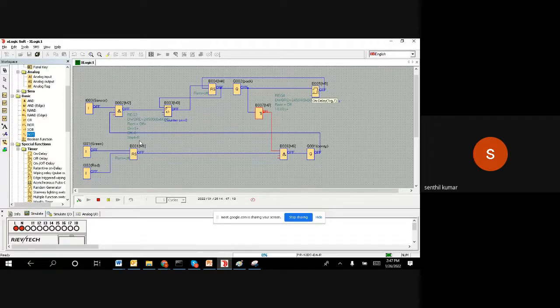Now we are going to simulate the logic. This is your initial logic. What we put in our brain is executing correctly, but we want to check whether this logic is correct or not, right? Let us check it now. I want to start the system, so I'm starting my conveyor. I pushed and released the button. When I push and release, I can see my conveyor is running.